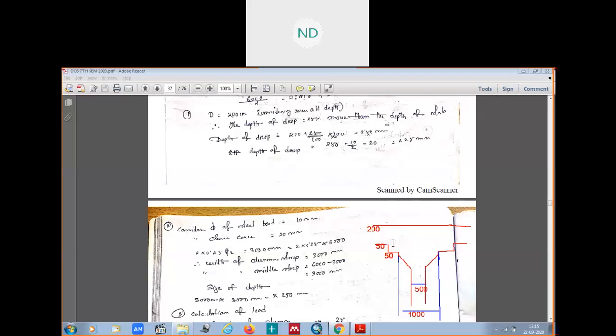You see here, this is the flat slab with the drop, and a small drop again here. Why? Such that this doesn't have a sharp edge connecting the drop. Then we have a column head, and then we have this column here, a 500 mm column, and the head is 1000. So here if you see now, this is your column with drop, column head, and your slab.